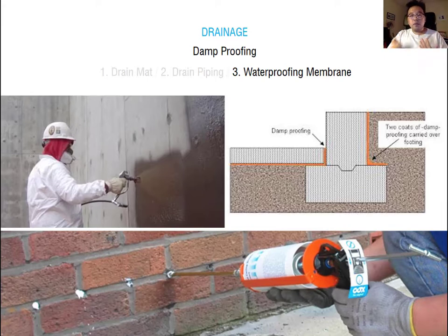Okay, so you remember the waterproofing membrane, and also we can have the vapor barrier. Remember the vapor barrier protects against moisture. The waterproofing protects against water. It's the same thing. Damp proofing at ground level and below ground level protects against moisture. The waterproofing protects against actual water.